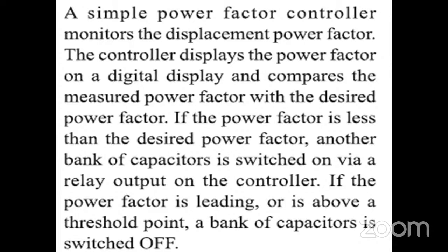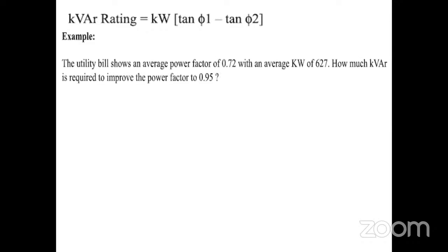Not only the lagging load, a leading load will also cause the same problem. It should be unity power factor. So the ideal case should be unity power factor. This is the standard formula for the kVAR rating of capacitors. You can just multiply kilowatt into (tan phi 1 minus tan phi 2).